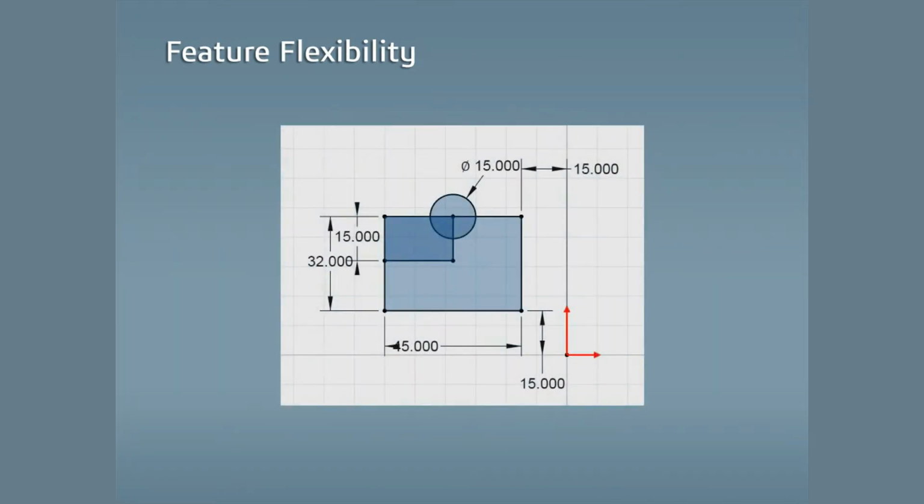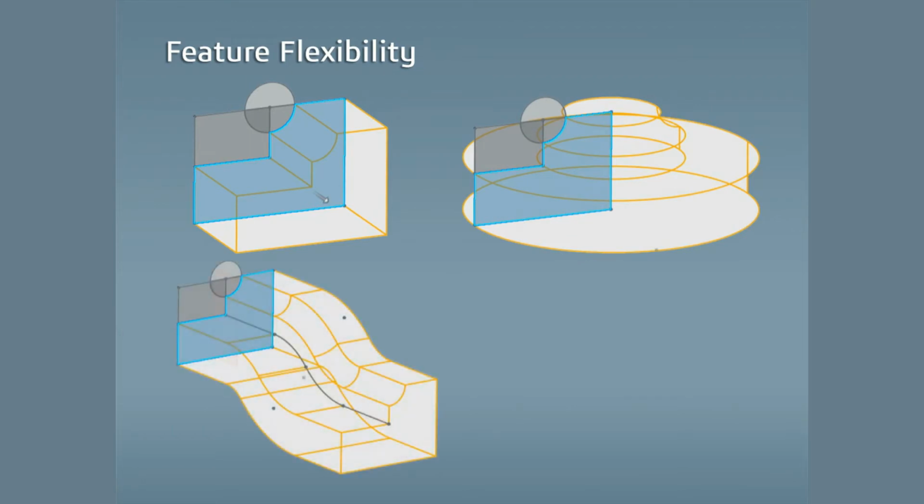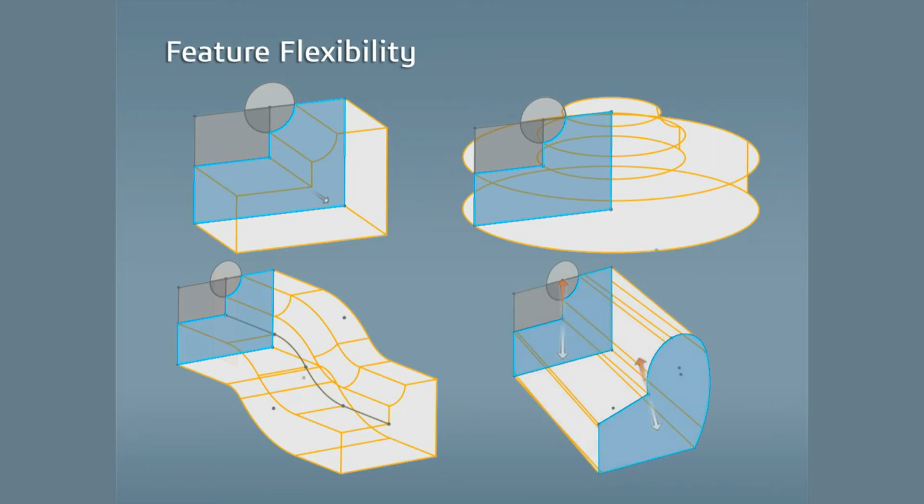Sketches are the foundation for many of the 3D features used in xDesign. These features take the selected sketch geometry and then move it along some sort of path through the 3D space. For instance, an extrude feature takes the sketch profile and moves along a line that's normal to the sketch profile. A revolve feature takes the sketch and moves it in a circle. A sweep feature takes the sketch and moves it along a custom curved path, which typically uses another sketch to define the path. And the loft feature connects two or more sketches together, creating organic, curvy geometry.